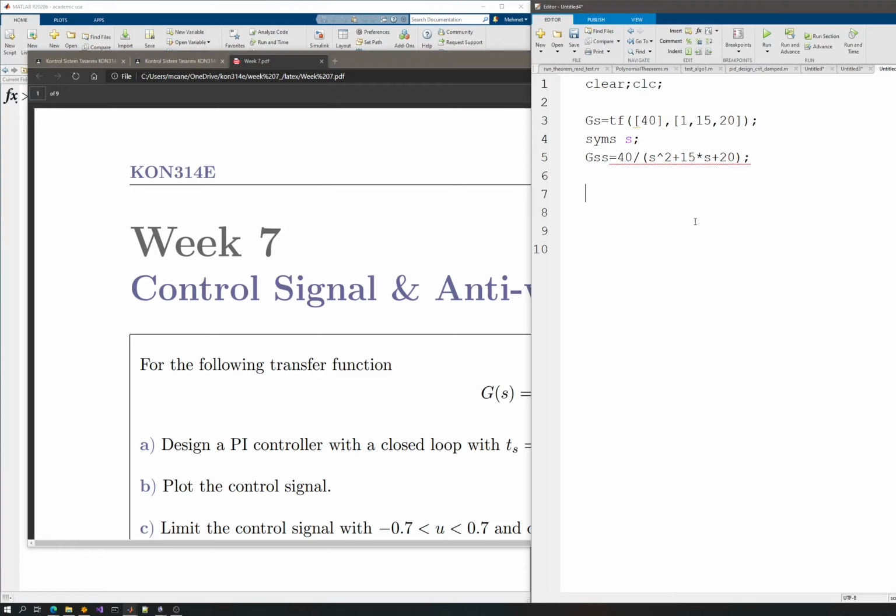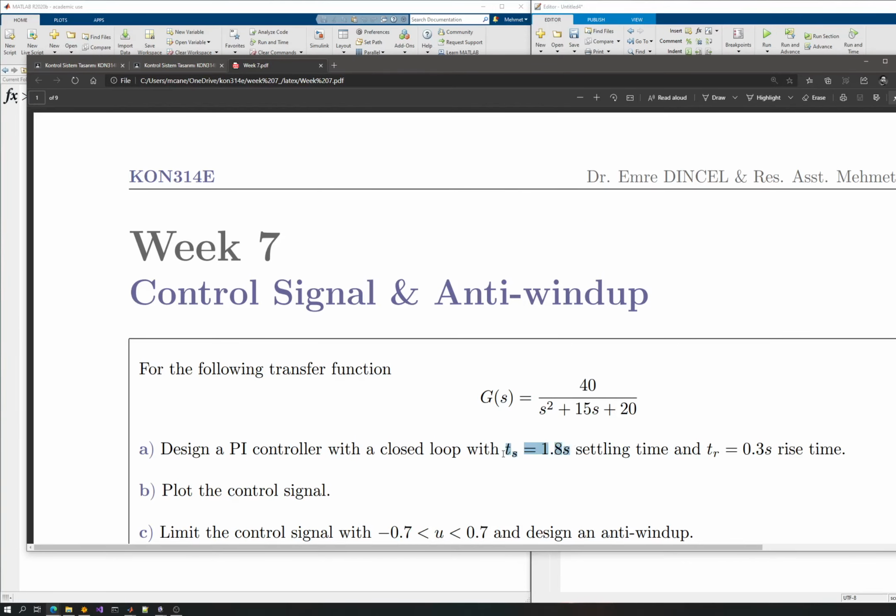And then, since I'm designing a PI controller, the best way to do this is to use the KP and KI coefficients, and I can also tell the symbolic engine behind the scenes that these are not complex values, these are real values, because if I have a PI controller, my coefficients should be applicable to the real world. So basically I need real values, so I can tell the symbolic engine. Now I have the controller structure, which I know. By the way, there are different ways to implement a controller design. So we can code it differently. I will mention that in a moment.